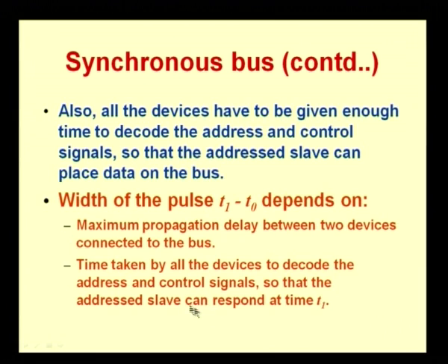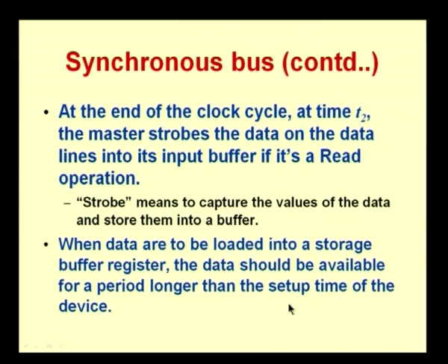Okay, it will take some time to get the data and put it on the bus. So that setup time also has to be taken into account. So t1 minus t0, the width of the pulse, is dependent on these two factors. Okay. And at the end of the clock cycle, that is at time t2, we said the master will strobe